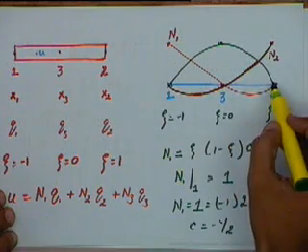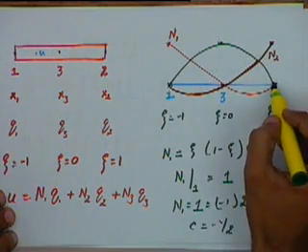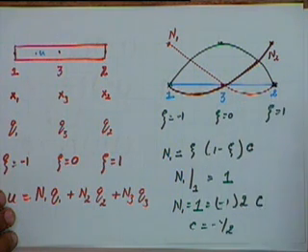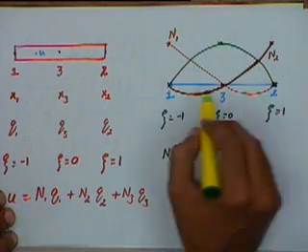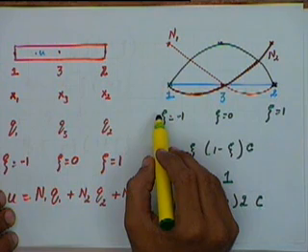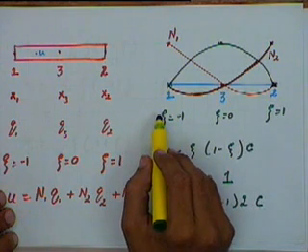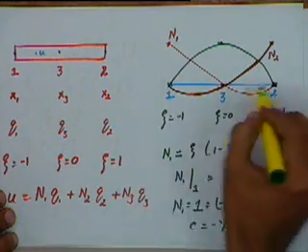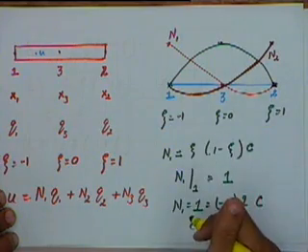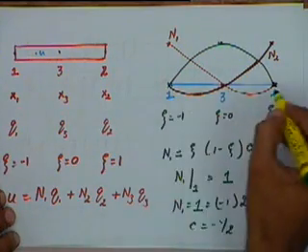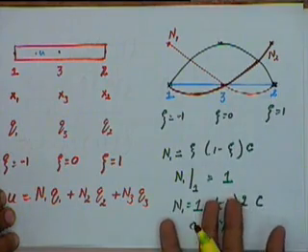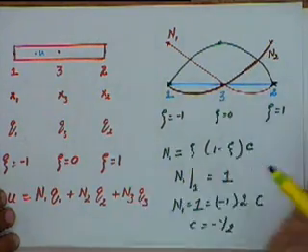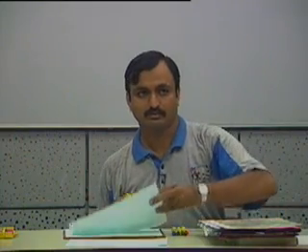No, that doesn't happen that way. What will happen is this is 1, this is 2, right? From the next element you will get this will be the first node of that. The second node will be at that end. So the second location as it is, we will see that the stiffness matrix of this will be larger. It won't be a 2 by 2 matrix. It will be a 3 by 3 matrix. So when you assemble a 3 by 3 matrix, we will see that this numbering will be more convenient. We will see that in the end. Because if I give 1, 2 and 3, strictly speaking you can always do that, but this numbering will be more convenient as far as assembling the matrix is concerned.